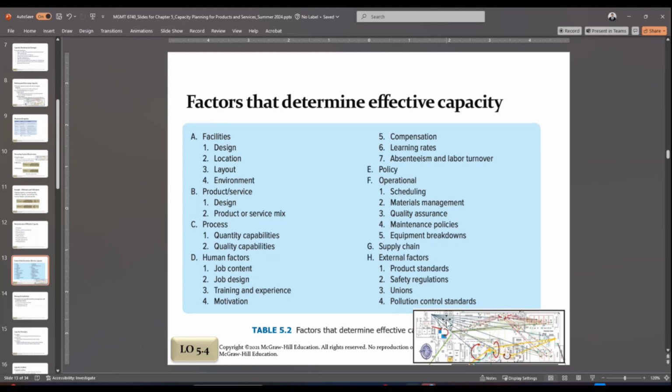And then location. Make sure the processes in the flow are placed very close to each other, so you are minimizing travel and a lot of hassles. That's the reason why getting a layout like this is important. Also consider the environment. Is there any smoke coming out during sintering when it gets heated to extremely high temperature? Are there any other fumes or gases coming out? Are they poisonous? Or maybe not highly poisonous, but in the longer term, might they have some effects?